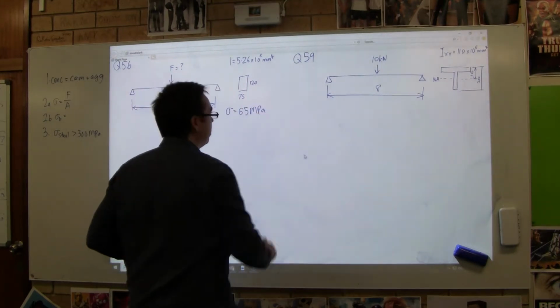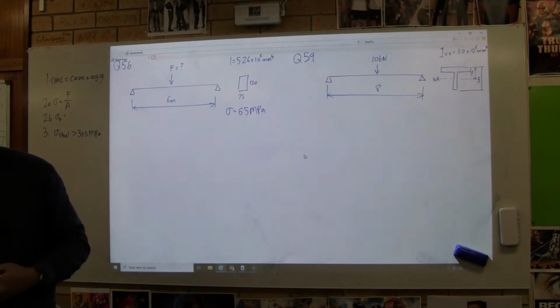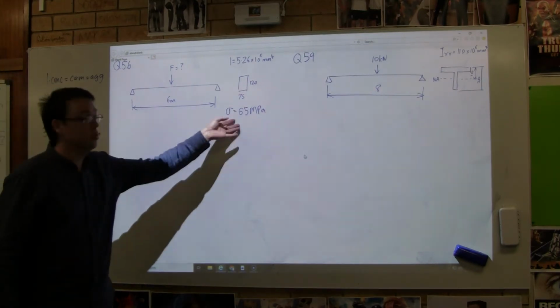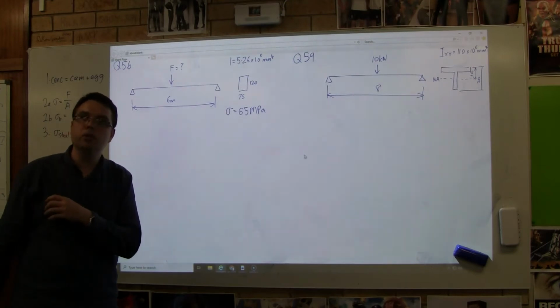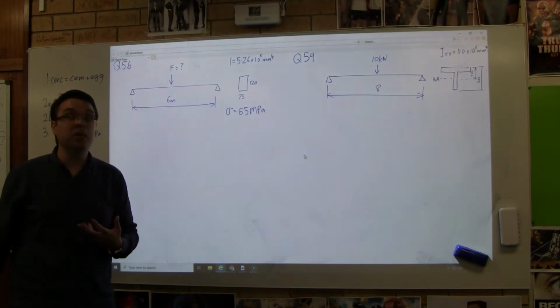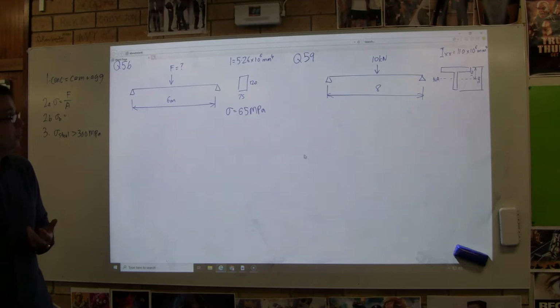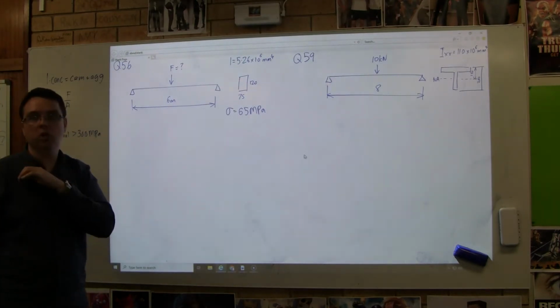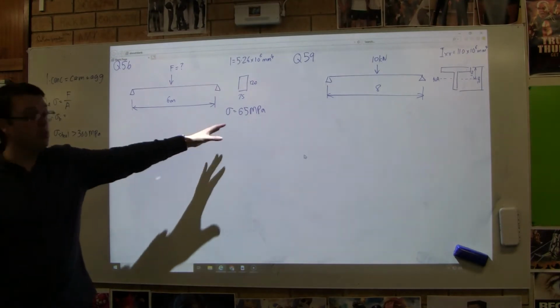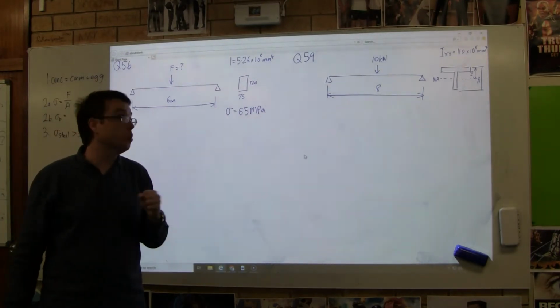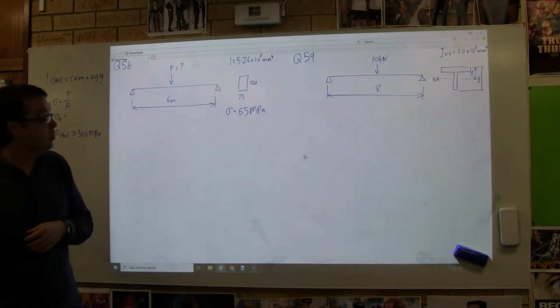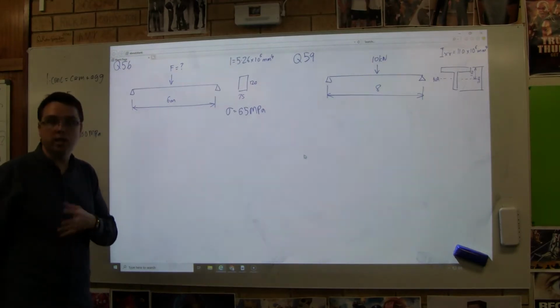Now, because we've talked about factors of safety, that might mean that the material can actually hold about 130 megapascals. So maybe something like aluminium, if it was made out of a solid block of aluminium. Probably unlikely. I wouldn't have chosen this value. I would have chosen a much lower value. I think a value of 5 or 6 MPa would be better if we're talking about something that looks like it's probably made out of timber. But let's run with it. Maybe this is a really highly engineered timber.